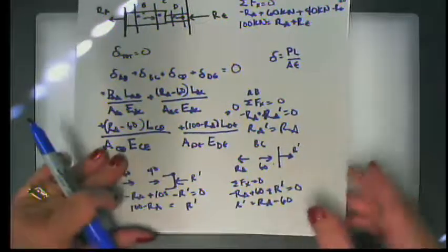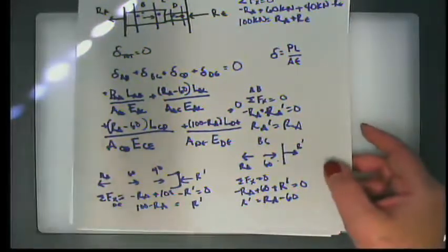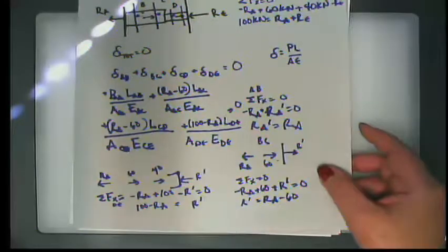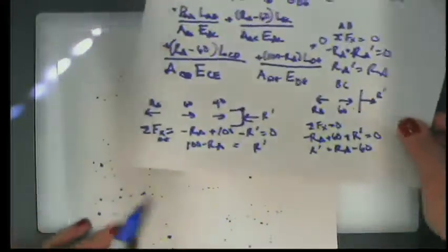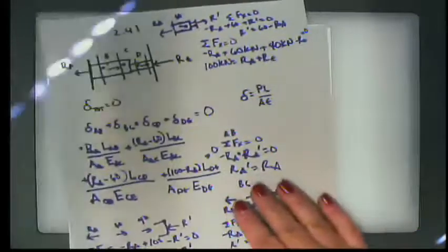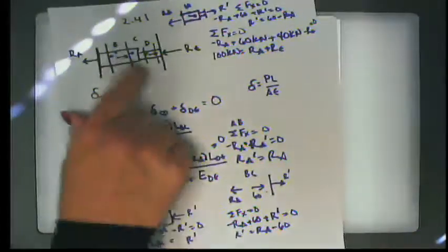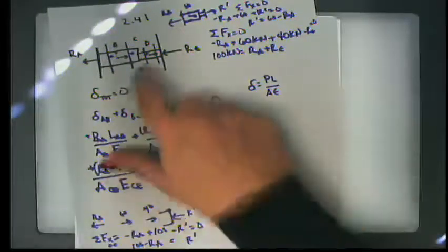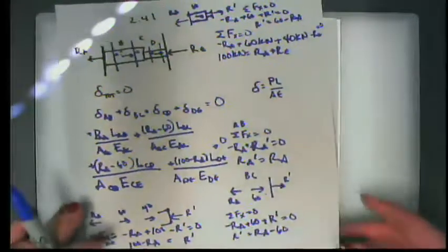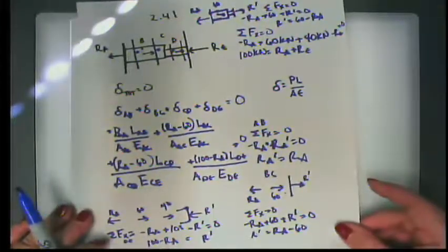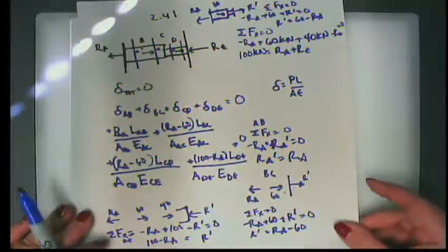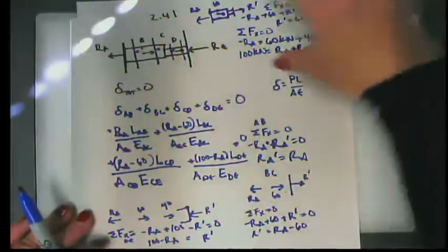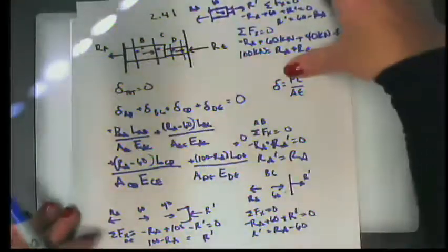But they're structured so that with the deflection analysis, you can find R sub A, the one unknown. Then you can go back to your original statics equation and solve for R sub E, because you know that the sum or the difference of them is that value of the force applied plus the force applied.